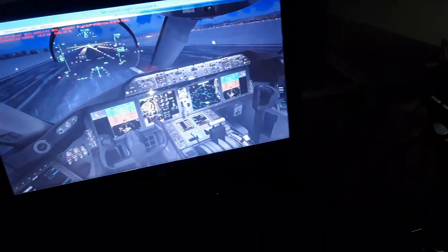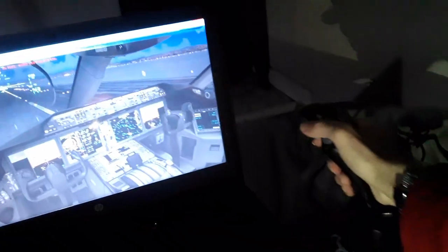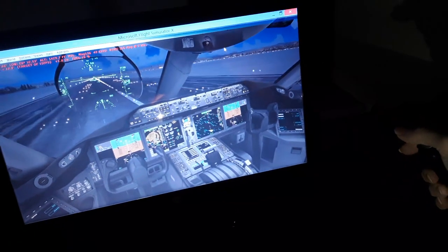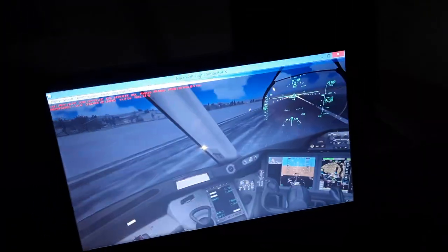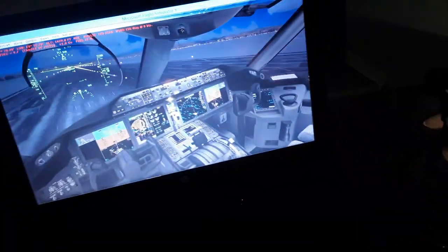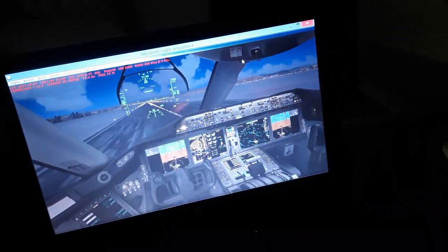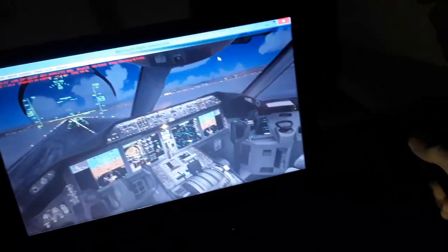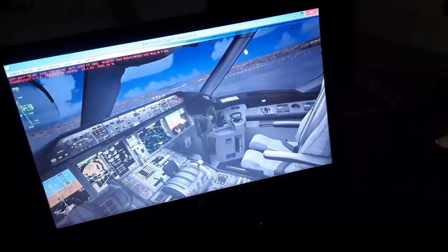We taxi for takeoff over here. So we advance over here the thrust levers, also here as you can see, thrust levers to full takeoff power, and also we can use the side stick down until 80 knots, so the yoke, push the side stick down halfway down, so 80 knots, release the side stick, 100, 120, 130, V1, V rotate, we pitch up like 9 degrees for rotation, very small pitch attitude for the initial climb, not hit the tail as we take off.